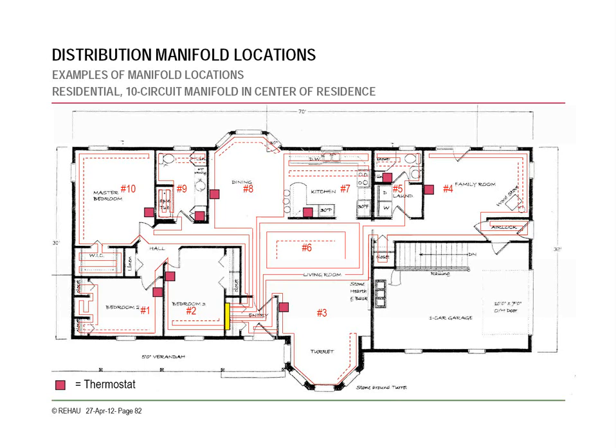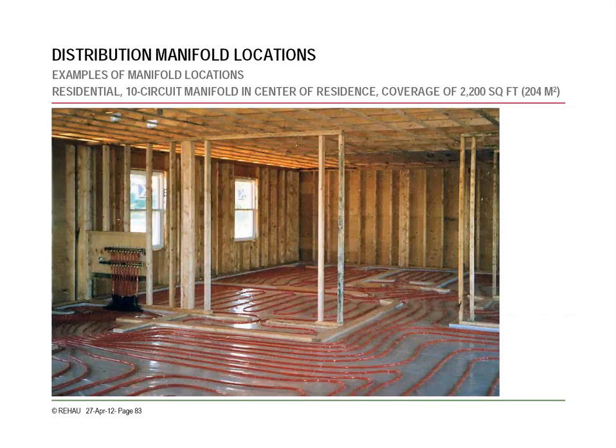But as you can see here, they're zoning it with thermostats in each of the areas, but all the tubing is running through one manifold. So in that case, you'd use manifold actuators, which we'll touch on a little bit later as well. And then here's a live example of the one we were just looking at, with all of the piping running back to this front manifold.